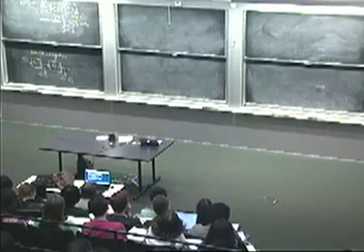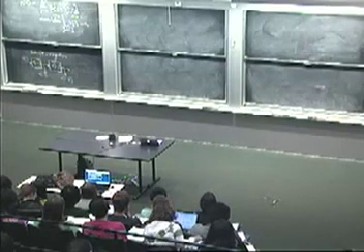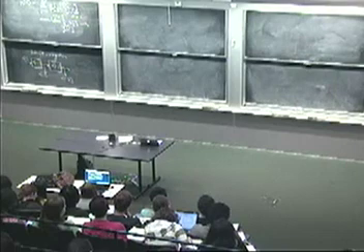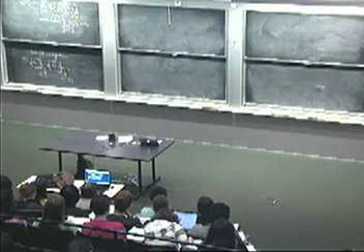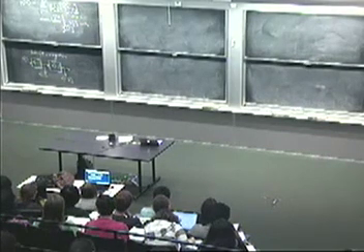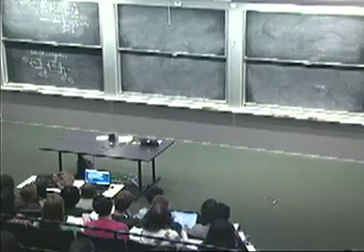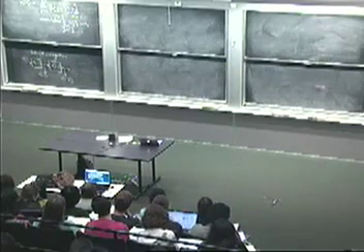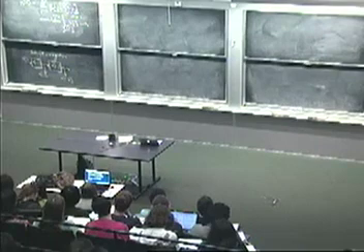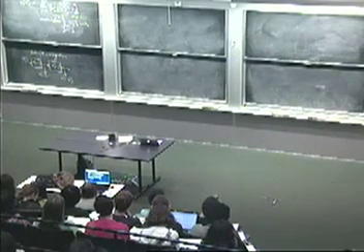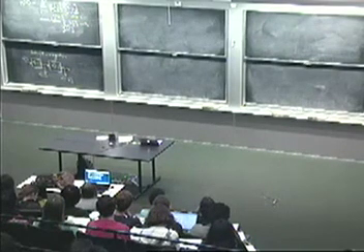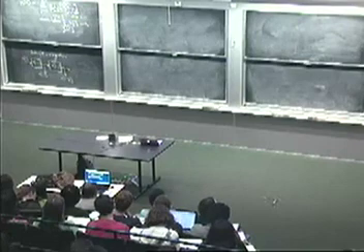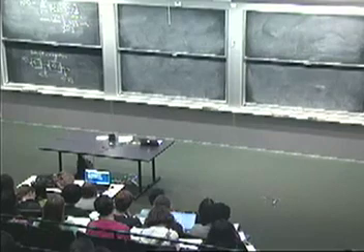All right? And so imagine this being the picture for every n. So you start off at time 0 and keep going. We refer to the state of the shift registers as the pair of numbers that we find in here. So if we're talking about x's that can be zeros or ones, the shift register combination here can be in one of 4 states: 0, 0, 0, 1, 1, 0, or 1, 1.